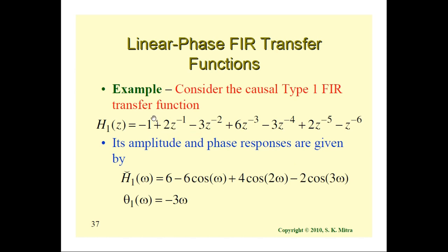Here we can see in this example a type 1 FIR transfer function, where you can easily see that the first and the last coefficient are same, the second and the second last are same, similarly the third and third last are same, and this is the center of symmetry.